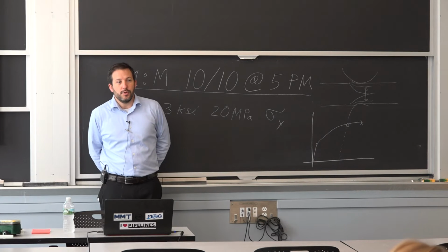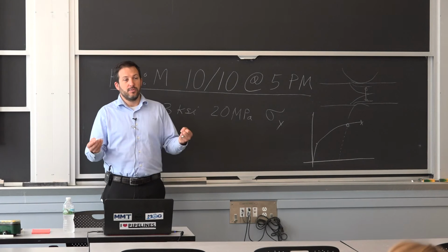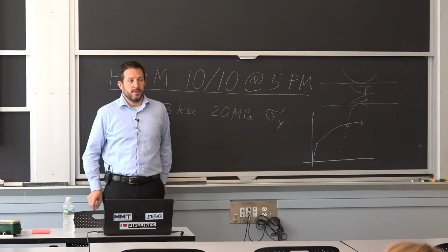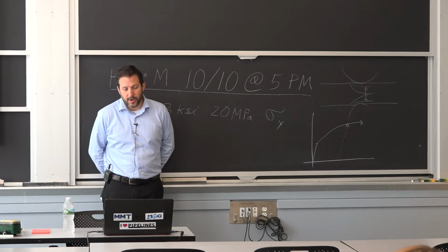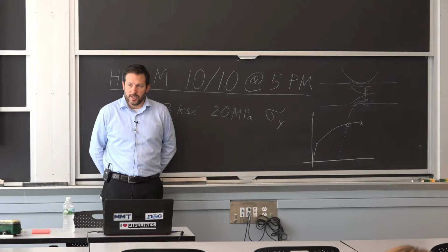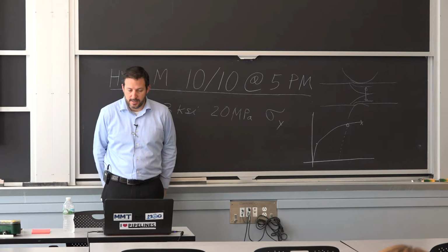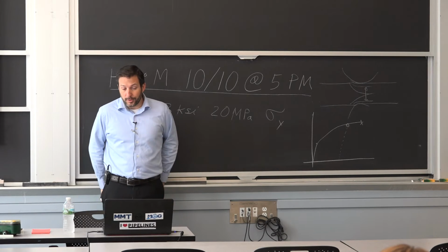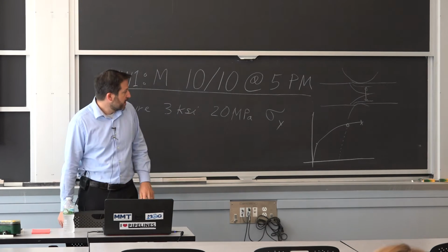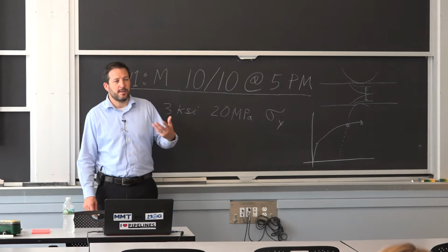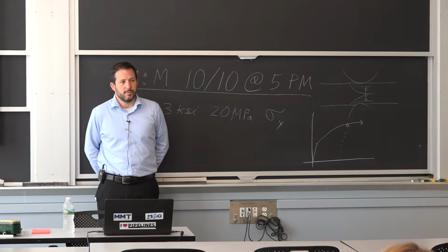So whatever you gain by this cold forming, you do lose it in resistance to fracture when you're forming it. So they take these in coils, like very large diameter coils for installation, and they have to be careful because they don't have something anymore that they can deform to 200-300%.